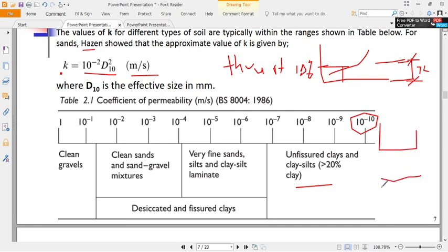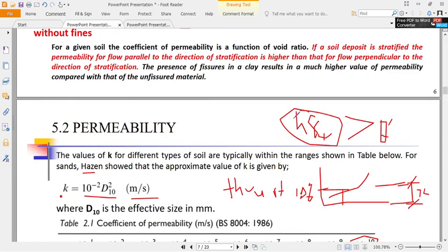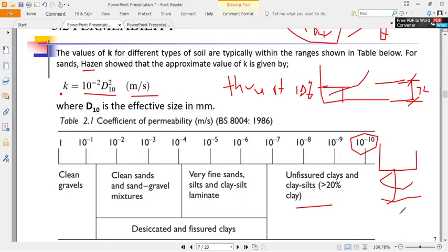So when you start excavating, you find that water will come out, because this may be the confining material, maybe an impermeable clay. When you reduce the weight, or the effective stress here, what happens? The hydro pressures, or the water pressures, will be greater than the effective stress. Therefore, heaving will occur. Water will start pumping out, or piping out, through the excavation. Is that okay?